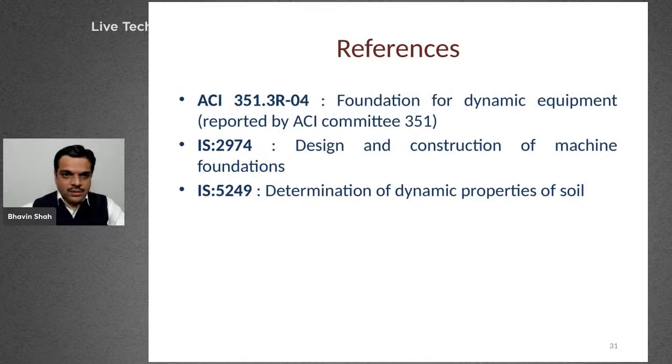Okay, so these are the few references which I just quoted in the document. So ACI 351.3R-04 you can refer, which is Foundations for Dynamic Equipment. Then IS 2974 for design and construction of machine foundations, and IS 5249 for determination of dynamic properties of soil.